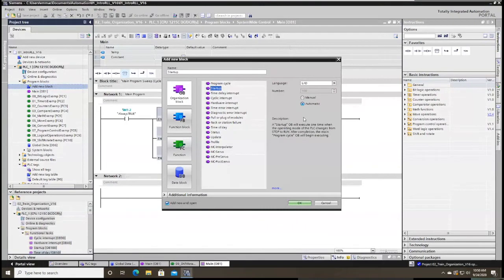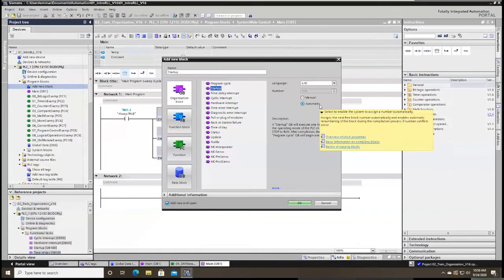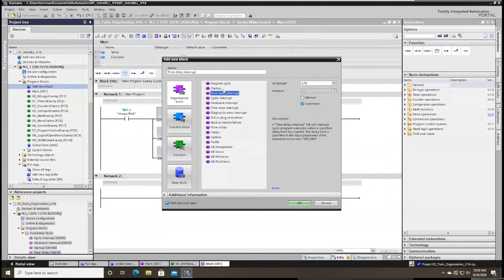You'll see there's a startup OB with a number of 100, so that when you start up the PLC, this is a higher value than OB1. It's OB100, a higher numerical value. So say the PLC started up, it would run OB100 first, and then it would continue down the ladder of different OBs, depending on if they're called or not, because while this is called at the beginning of the PLC starting, some may not happen every cycle. Some may happen, for example, at a certain time or day.